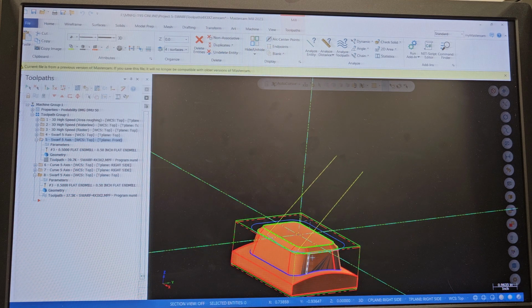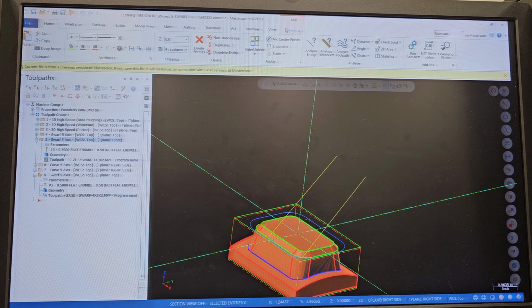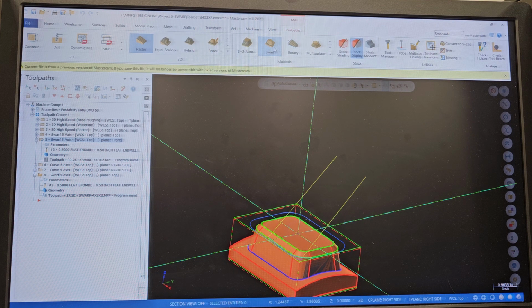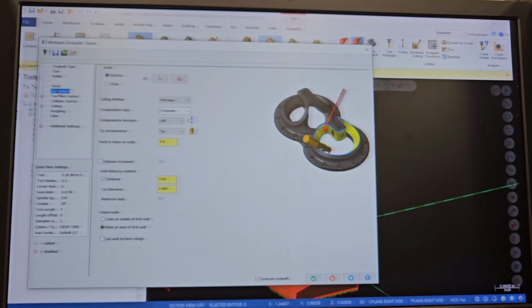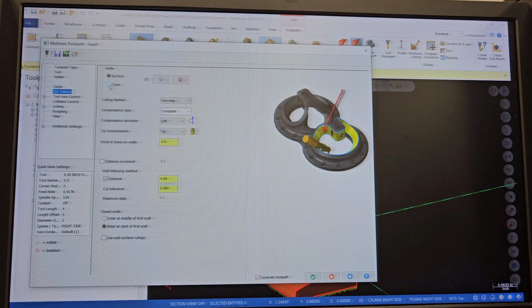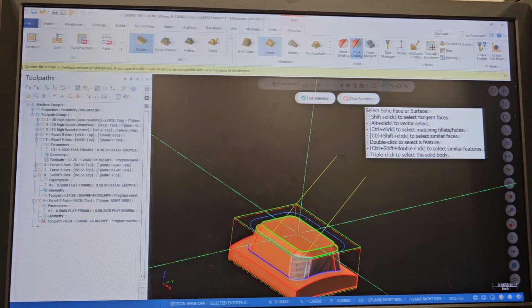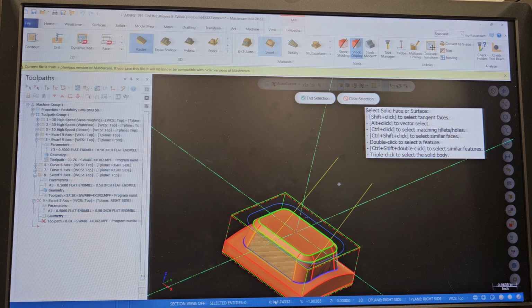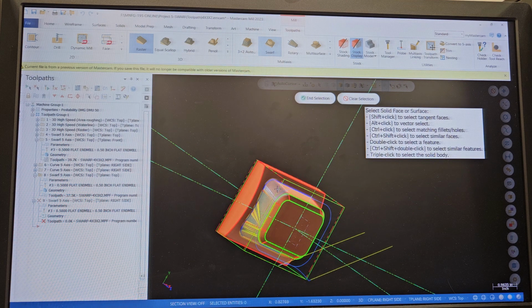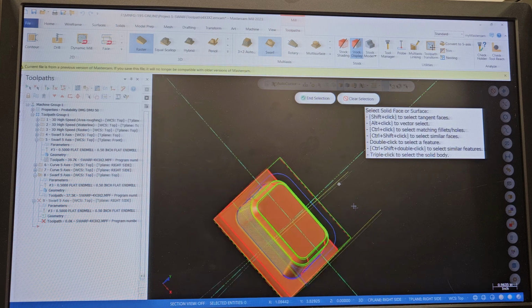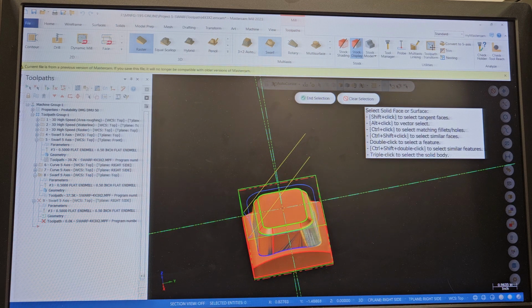Let me show you how the chain works. If you go to the same toolbar, swap, and same half an inch envelope, and cut pattern. This time, if I'm going to pick chain, you want to pick surface like we did last time? Yes, we can pick surface 1, surface 2, surface 3, 4, 5, 6, 7, and 8. Hit OK.